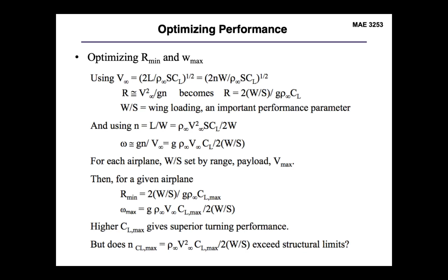Now, when we start to look at this from the standpoint of optimizing the performance of the aircraft for these various maneuvers, again, one thing we have to recall is all these pull-up and pull-down maneuvers considered have been instantaneous, really in contrast to the sustained maneuvers that we saw earlier. For these instantaneous maneuvers, the thrust limitations that we see for things such as the banking maneuver aren't really relevant here. We have to think about these instantaneous maneuvers essentially being initiated by a very quick and sudden change in the lift when we increase the angle of attack for this maneuver to actually occur.